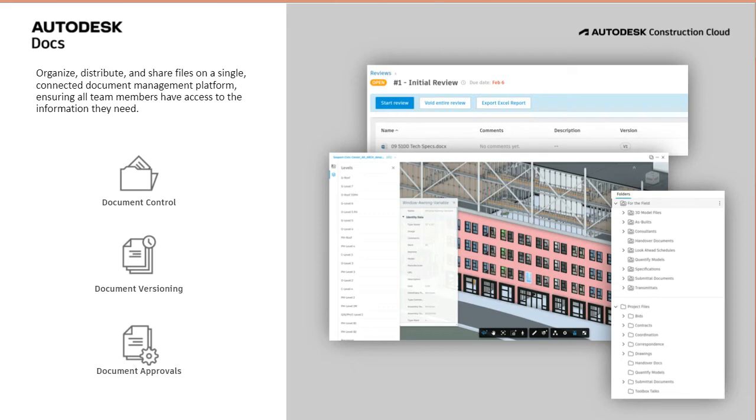You can see here on this slide as well, it's got a very, very robust model visualization tool. We call it the large model viewer. And within that, you can segment your model based on a number of different elements, whether it's levels. You can look at individual elements based on their type. You can identify all of the property information associated with that. So in that image there, it's a little small, but you can see that we're looking at a specific window, and it's got all the dimensioning, any manufacturer information, all the information that would have been put into the model in the first place in Revit can be visualized here.